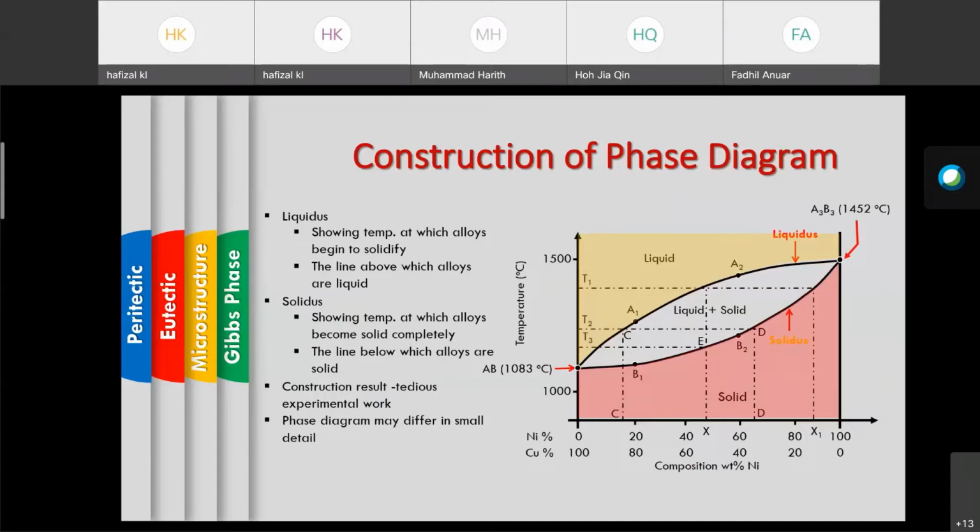Actually, the process is we will set the composition first. Let's say we combine 2% at a time, starting from 0% of the foreign element, and then look at the changes of the temperature. We will look at the solidification start and solidification end. And finally we will look at the various lines, and then we can overlap them and construct the phase diagram.